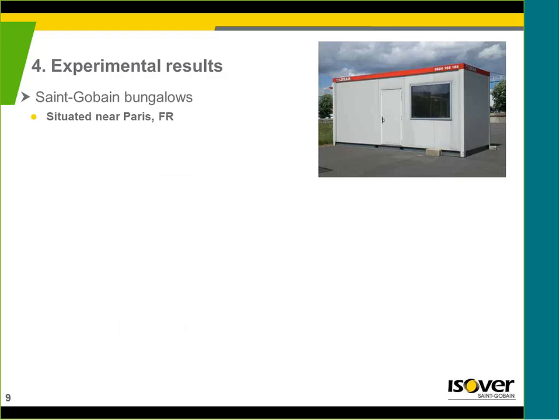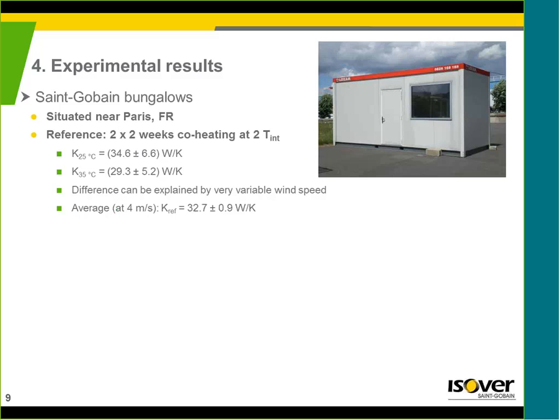So I was talking about the co-heating test that we did near Paris in bungalows that are rented right now by the Saint-Gobain company. We did, as a reference, 4 weeks of co-heating, 2 weeks at one internal temperature and 2 at the second one. We measured the 2 values. We had rather high uncertainties on the results for both of them, but the differences we found could be very accurately explained by the wind speed, which changed a lot during the different tests.